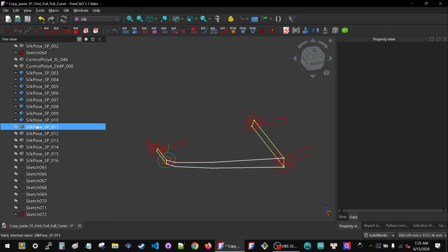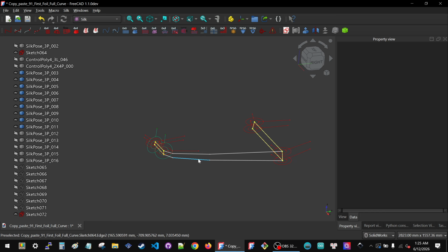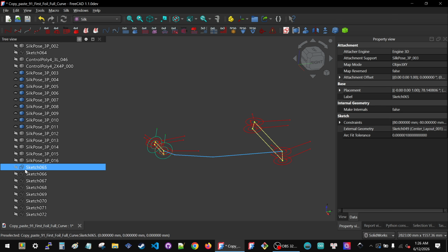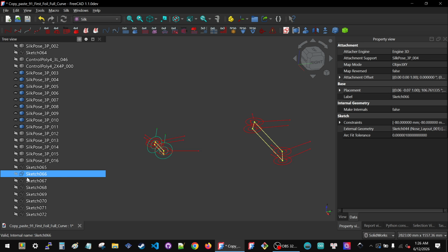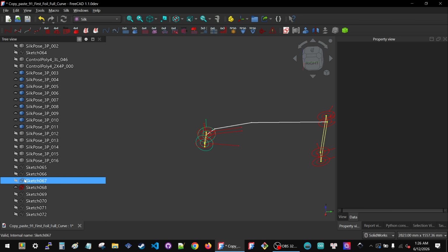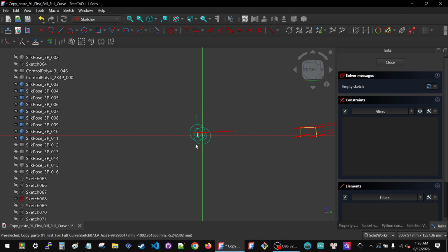So I have this one. So what's the next one? The next one is this guy. It's on the bottom, and I'll be more or less copying this guy, but it's going to be in the way. What I do want is this sketch, because I'm going to be importing from this sketch. Okay, so I'm on this plane, create the sketch, objects XY, right here.